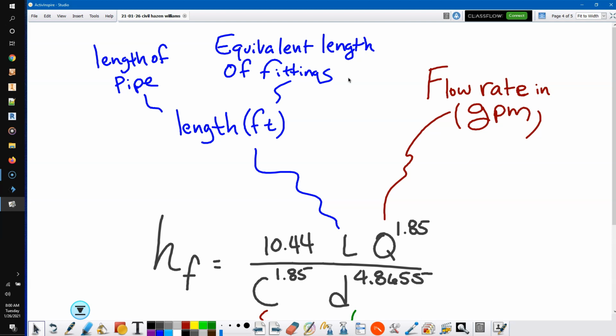And then you add all that together. So it's kind of like doing a little budget. And then you take that number of feet. So for an elbow, sometimes it's adding 14 additional feet for every elbow. So if you had 16 of those, you would do 16 times 14, and that's how many feet you add to your system to make it equivalent to straight line pipe. So that's the two components that go into the length of feet.